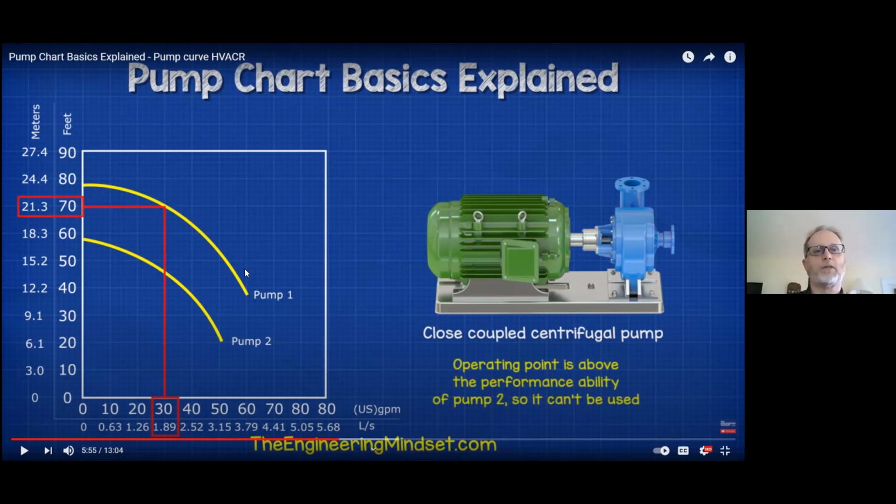The manufacturer supplies the curve for every pump, and some will have multiple curves based on different impellers. The engineer then chooses the best spot. And again, they want the highest efficiency. The curves will vary based on the design of the pump itself. But basically, as soon as we know which pump will suit, we can then specify that and build around it. But it's these 2 factors, and that's how we visually space them out.